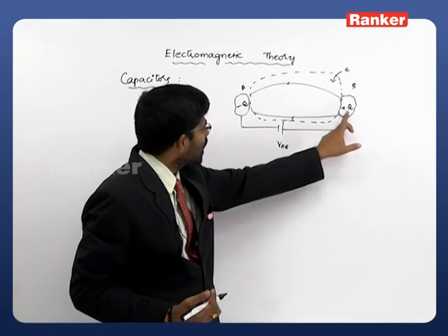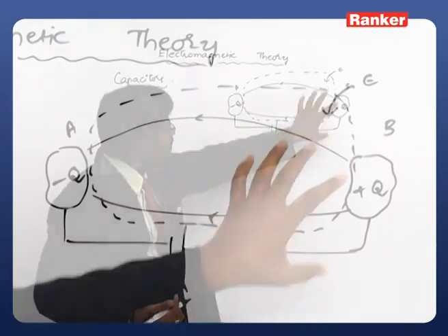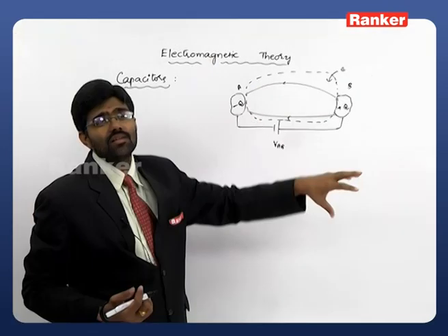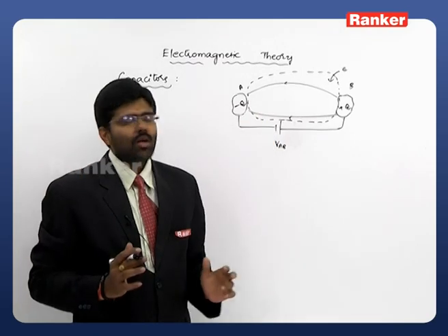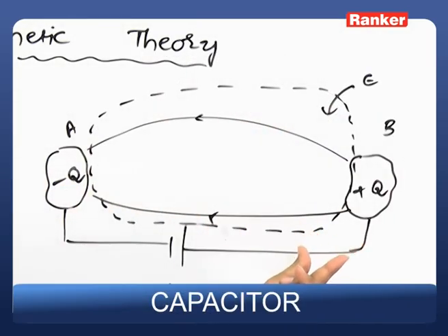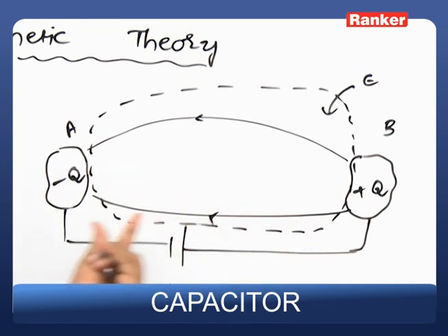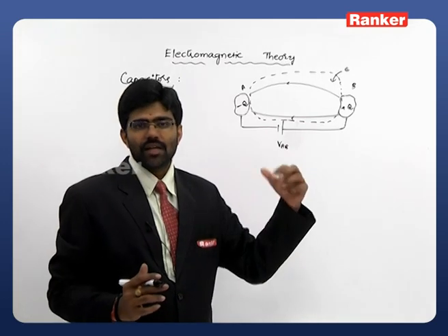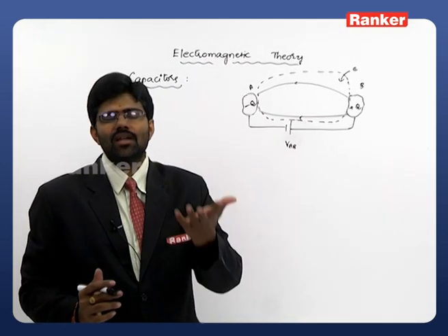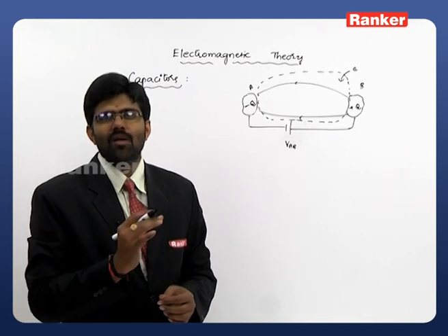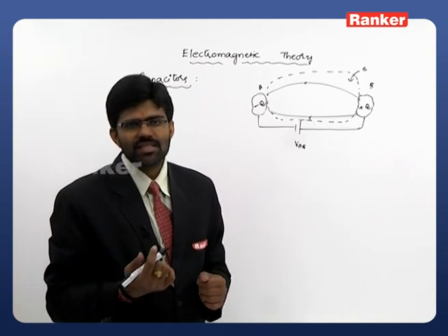What we have is a charge, and that charge is generating the electric field. That electric field can be stored inside the dielectric slab we are placing between these two conductors. Simple. This arrangement is called the capacitor arrangement, and it has a capacity. Why is it called a capacitor? It has a capacity to store electric energy. How is that capacity defined? That capacity is called capacitance.